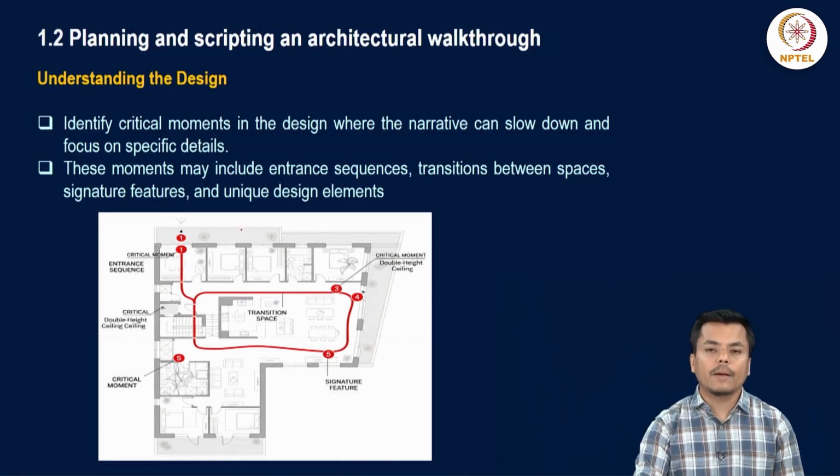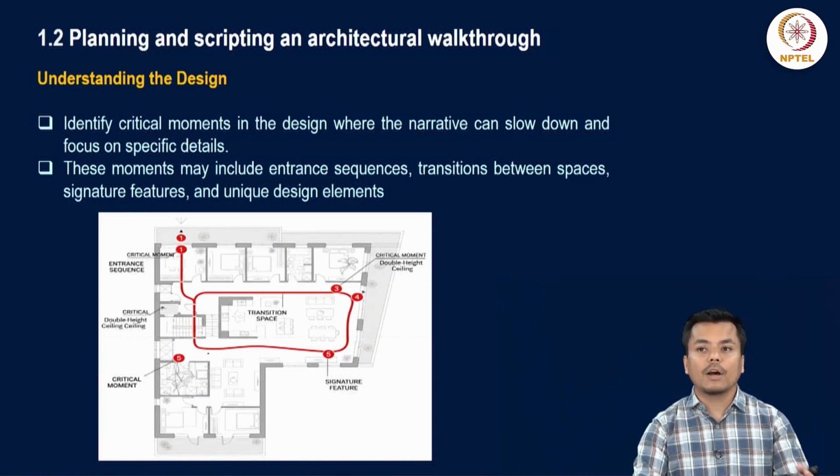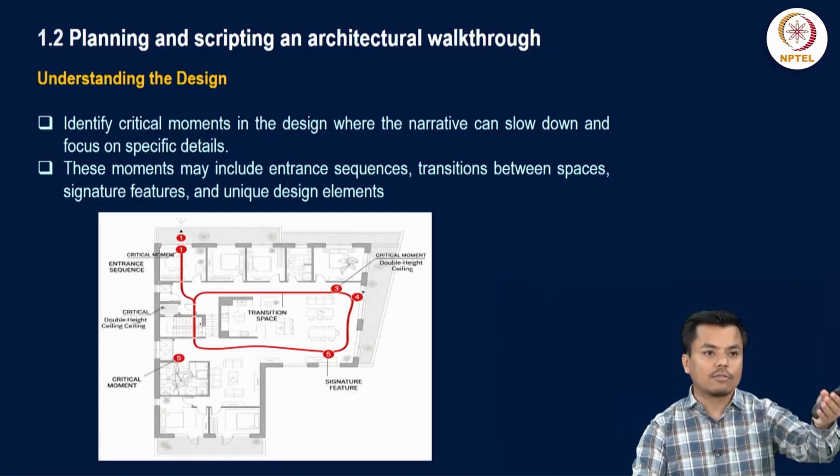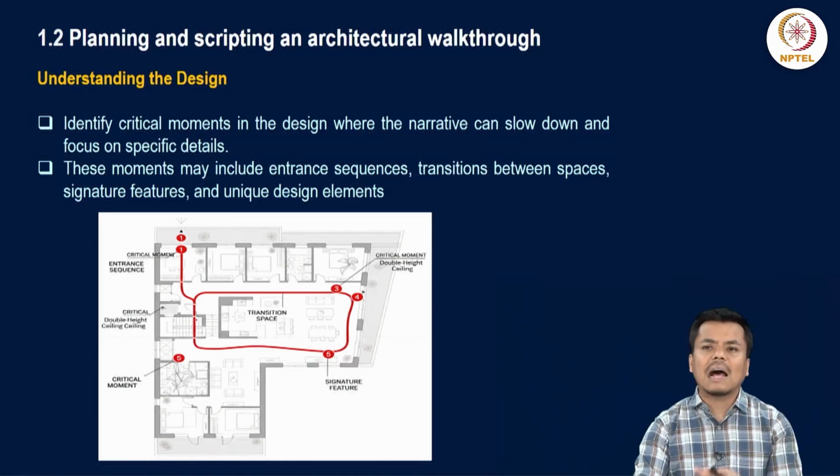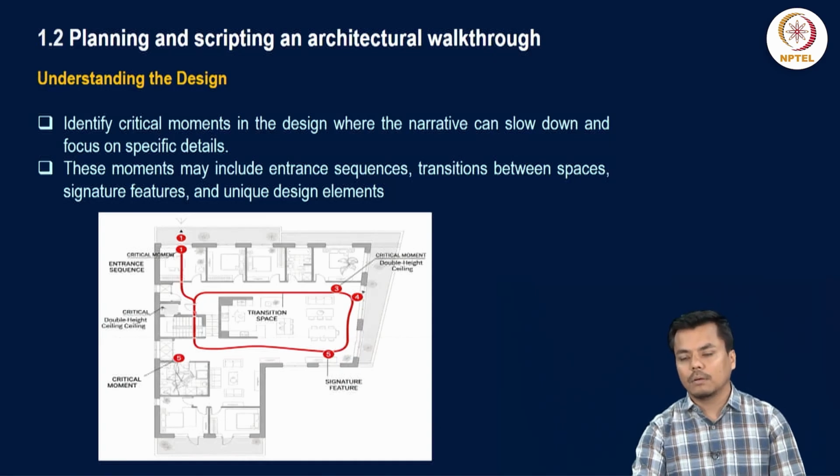When you start preparing a walkthrough, it may look something like this: the places where you will pause and view will be marked, and then the movement pattern will be decided. How you are moving from one place to another also has to be showcased in detail. You cannot just cross the wall and enter the other space directly. You have to always follow the corridor, enter through the door and then come out, or else it will look highly animated, and if it gives that kind of perception, then the person will not be able to relate to the walkthrough videos in a better way.